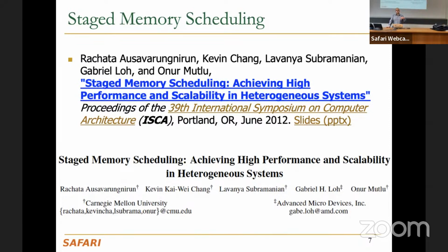At the same time, these are kind of error tolerable. So for GPU in general, it's mostly important that you provide quite good bandwidth to access memory. But for the latency, as long as DRAM access latency is in some tolerable region, you can hide it using scheduling threads, basically.